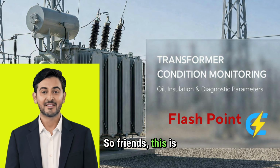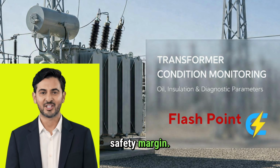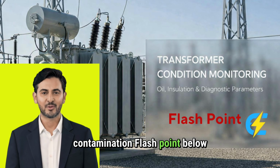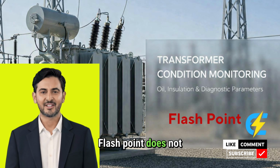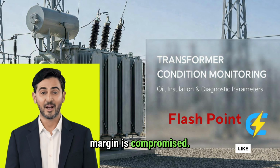So friends, this is the real meaning of flashpoint. Flashpoint is not about performance. Flashpoint is about safety margin. Remember these rules forever. High flashpoint, low fire risk. Falling flashpoint, volatile contamination. Flashpoint below standard, oil rejection. Flashpoint does not recover by filtration alone. Once it drops significantly, the oil's fire safety margin is compromised.